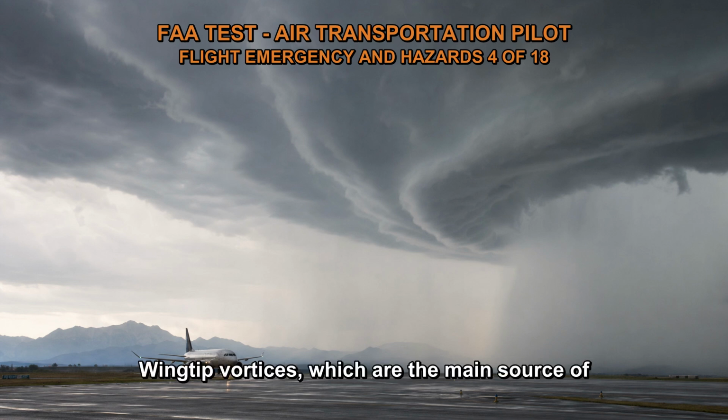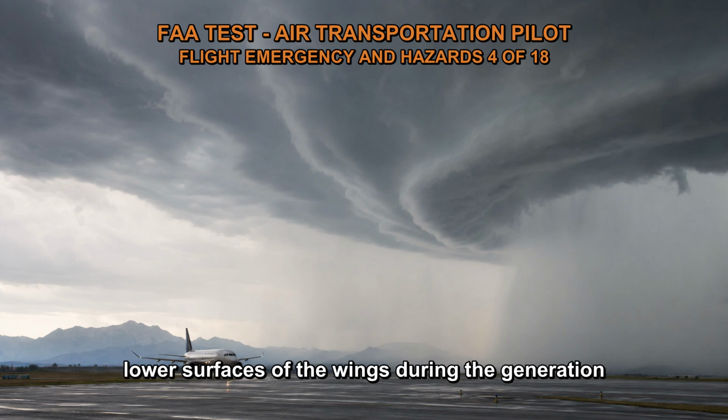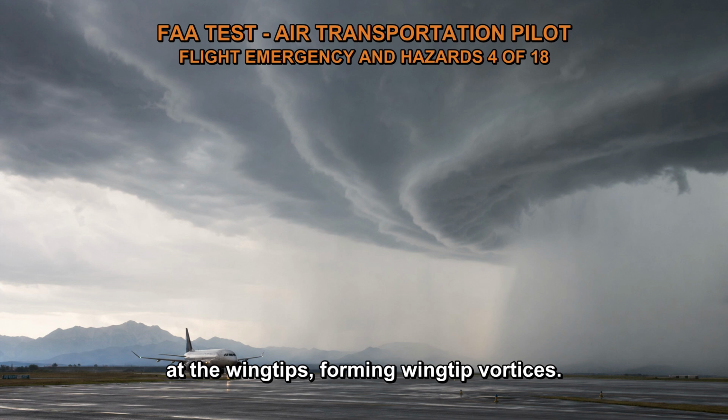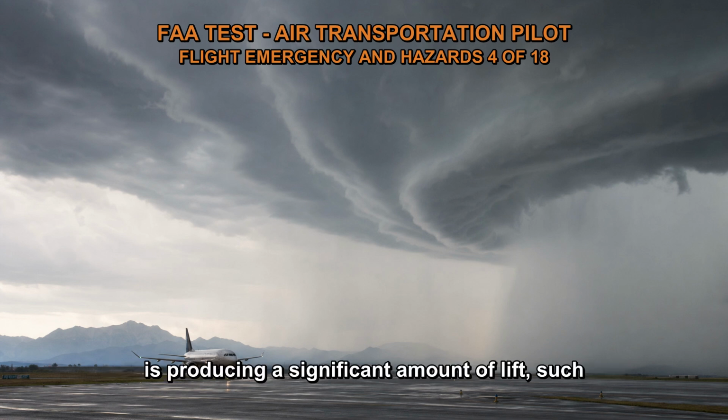Wingtip vortices, which are the main source of the hazardous turbulence, are formed as a result of the pressure differential between the upper and lower surfaces of the wings during the generation of lift. As an aircraft generates lift, the air flows over the wings and creates a swirling motion at the wingtips, forming wingtip vortices. These vortices are more pronounced when the aircraft is producing a significant amount of lift, such as during